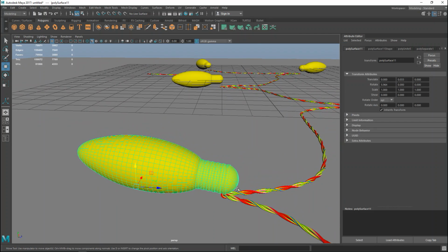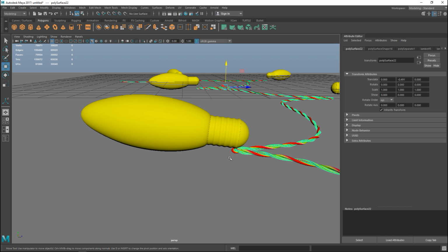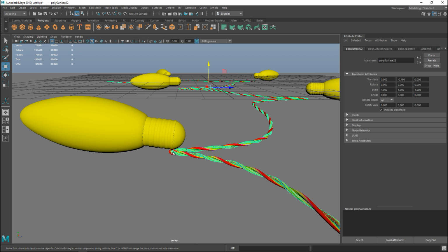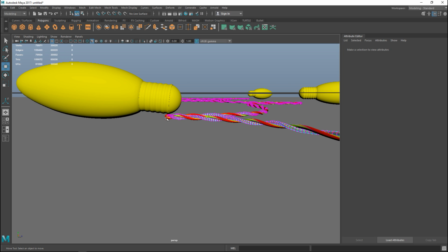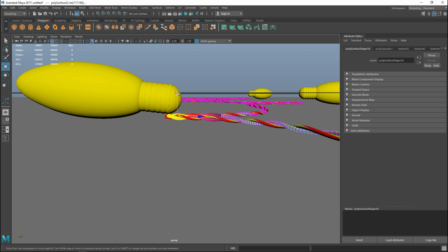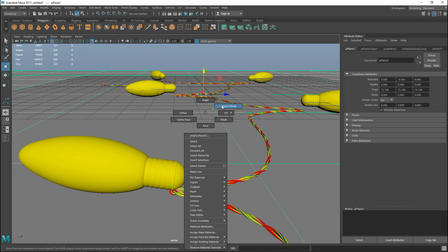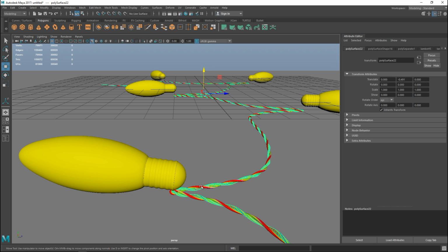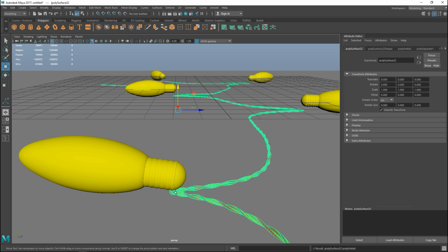And so what we're going to do next is we're going to take our cable here, and this area needs to rotate upwards so it's fitting into our light. Okay, so I'm going to right click at a vertex, and I'm going to hit B for soft select. I'm going to drag select this area right there, and hang on, this guy should be combined. Hopefully it is. Should be one object. Okay, so mesh and combine, there we go.